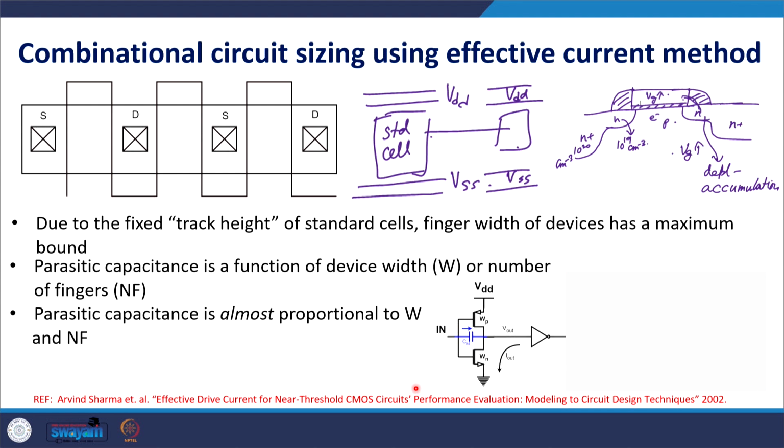This is one standard cell with VSS here, VDD here, and this is another standard cell with VDD here, VSS here. When you bring them together, these VDD and VSS lines merge, and the output of this and the input of this abut with each other. For example, if this is the inverter chain that we are discussing and these are the inverter standard cells, they would abut with each other, the power supply rails would merge, and each standard cell would look like this.